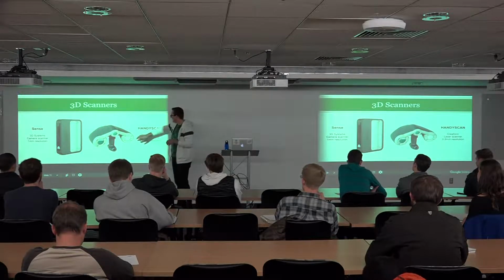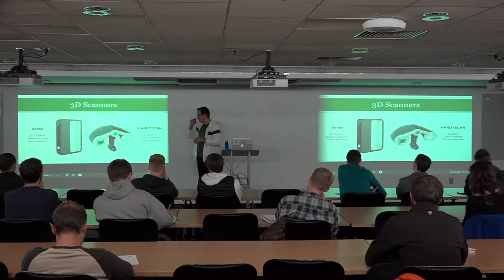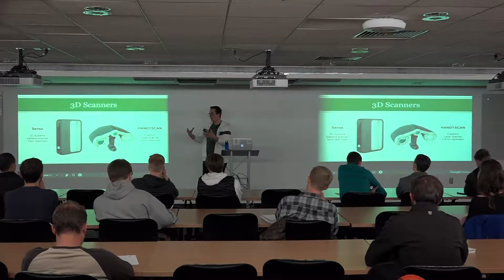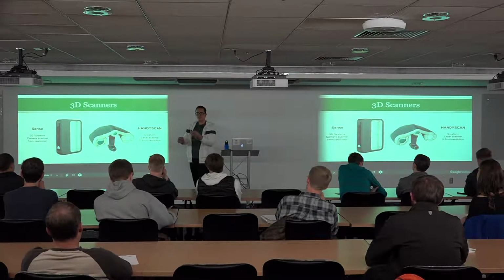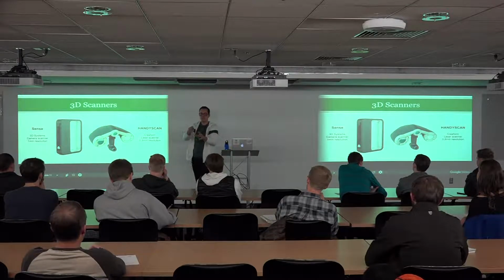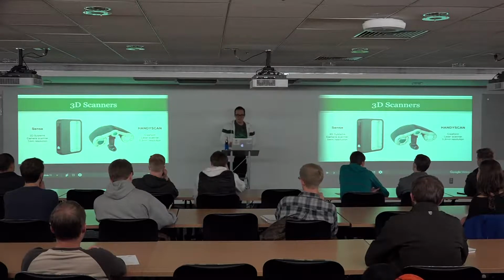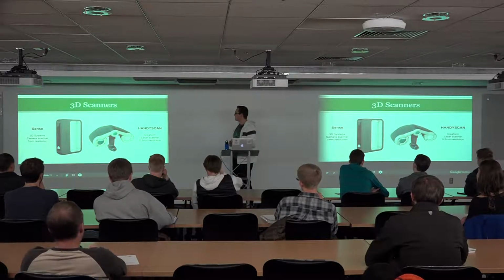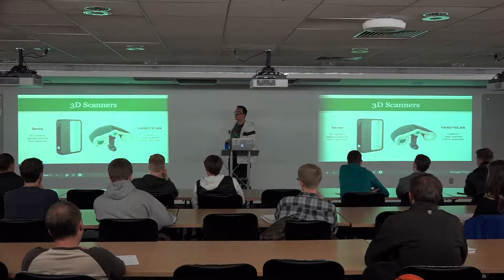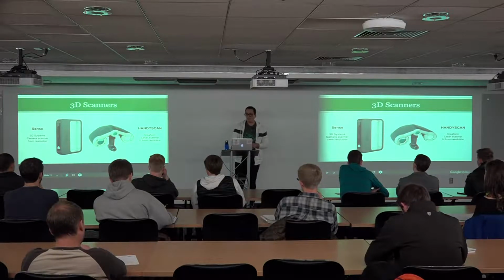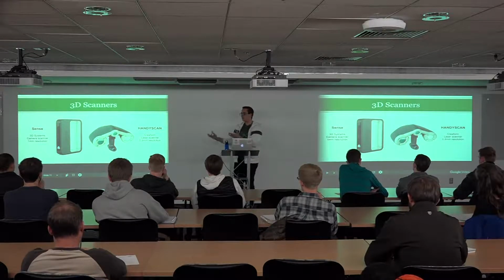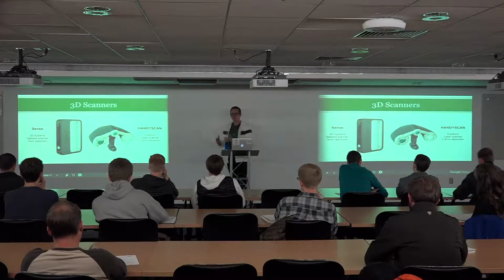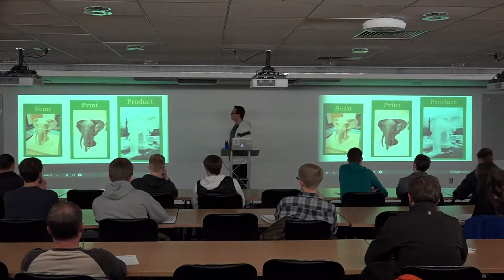The Handy Scan is a laser scanner, and requires a little bit more as far as positioning. So we have a platform with little positioning dots all over it so that it can track those dots in 3D space and scan your object. And we have scanned actually fossilized teeth and diamond rings and all kinds of crazy things. So if you need to get a 3D scan or a replica of something that's kind of complex that you can't design otherwise, scanning it is the way to go.